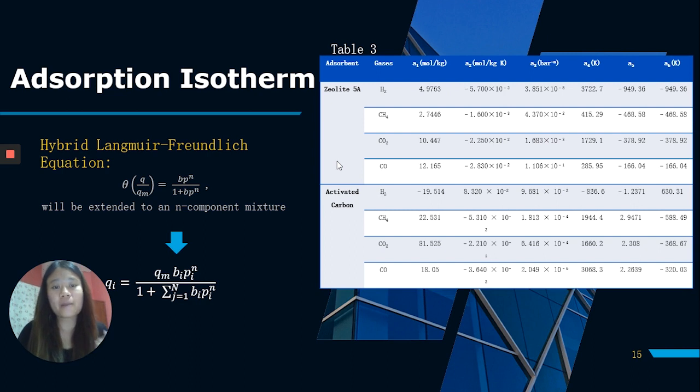To predict the best isotherm equation or model, the one which gives the best linear line will be chosen as the adsorption isotherm in the hydrogen enrichment process. However, since the operating pressure in the hydrogen enrichment unit exceeds atmospheric pressure, the linear isotherm or Henry's adsorption isotherm is not valid in the process.